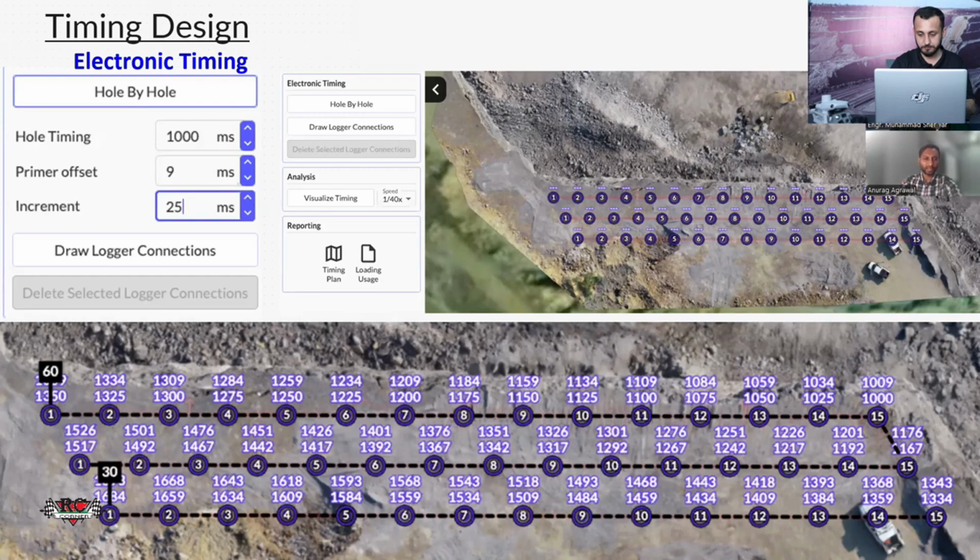And after that, you can analyze the throw direction, the materials according to the time design, what the delay time is, and with your 8 millisecond delay time, how many holes are firing, as well as the delay between the tags. All the design can be easily done.